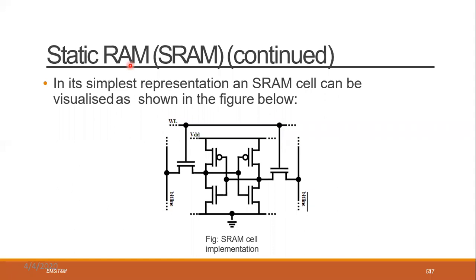So under RAM you got three types. One is SRAM, that is static RAM, and another is DRAM, dynamic RAM. Then the last one is non-volatile RAM, which can be considered as ROM also. Why is it known as non-volatile RAM? It has a small battery behind it that continuously provides power to the RAM. When the RAM has power continuously, it can retain the memory content. Because of that, it is known as NVRAM, non-volatile RAM.